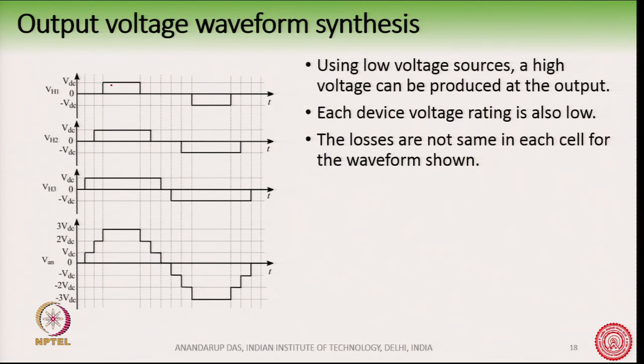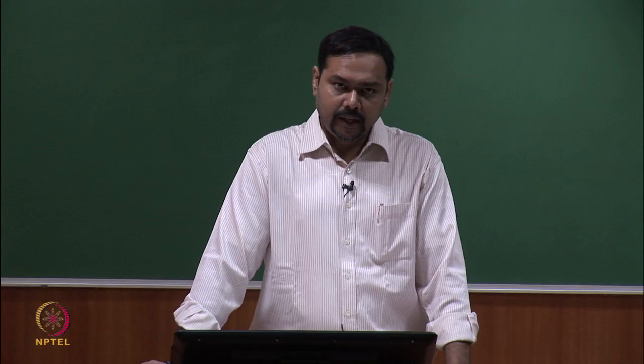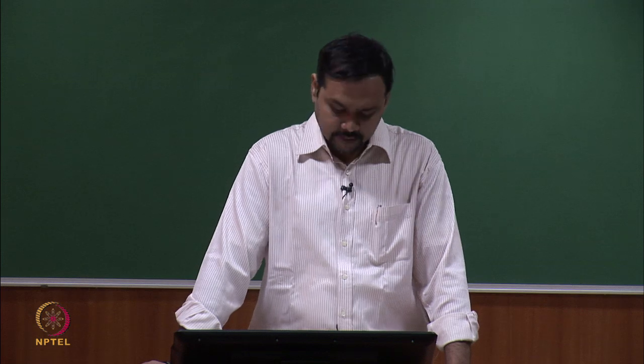So, the switches are working for unequal duty ratios in cell 1, cell 2 and cell 3, which is evident from this waveform. And so, the losses incurred in each cell are different, and we have to make some special arrangement so as to make these losses the same. We will see this PWM technique, in particular level shifted PWM.